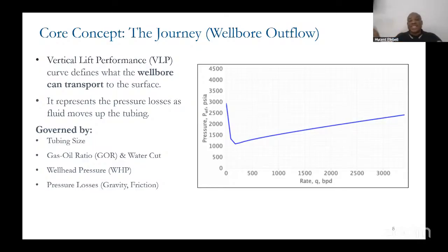So as your velocity is increasing, maybe you are in gas lifting and your gas lift system has too much gas, then a time will come where instead of the gas helping your fluid, lightening it and helping you to lift it to the surface, the pressure drop because of the increase in velocity as we are injecting more gas now overcomes the advantage you are getting in reducing the density of the fluid.